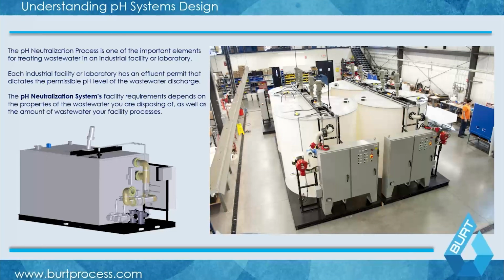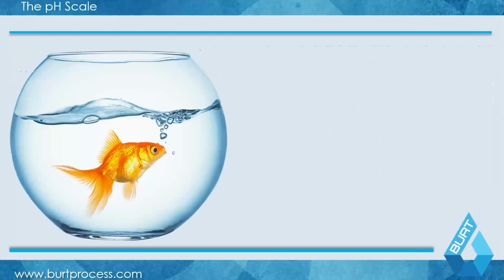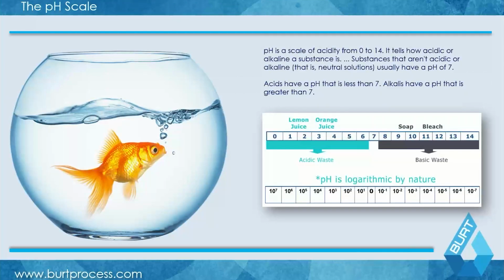For those who are unfamiliar, a pH neutralization system is a process system installed on the final drainage of any laboratory or healthcare, semiconductor, pharmaceutical, food and beverage, or institutional research facility, even in some larger high schools, where people are utilizing chemicals, whether acid base, laboratory, or wet process chemistry. This is a system that monitors, treats, and then allows for safe discharge of waste into the sanitary sewer system so you are discharging your waste in spec. The ideal range for pH is defined by region, but generally falls in the 6 to 9 pH range.